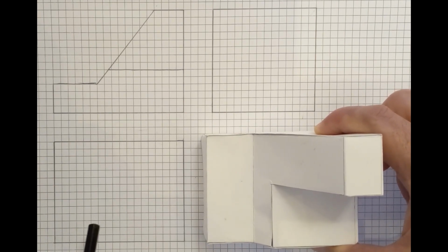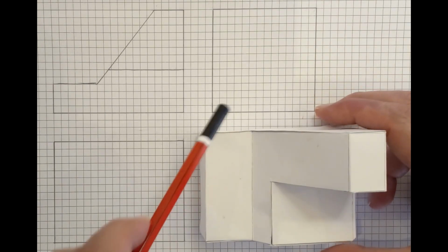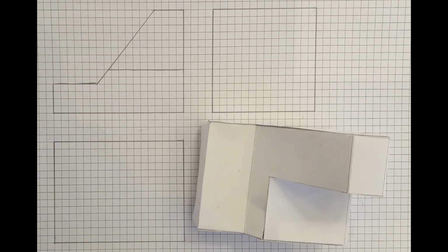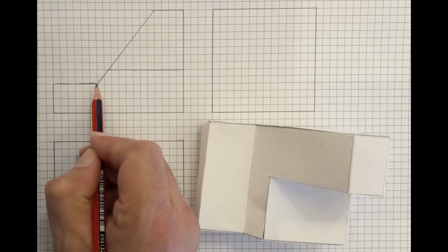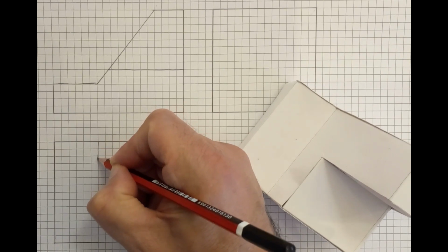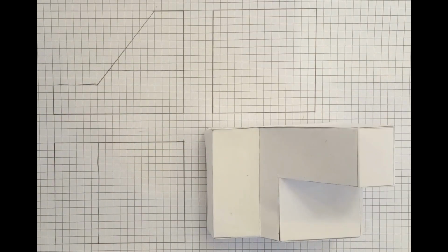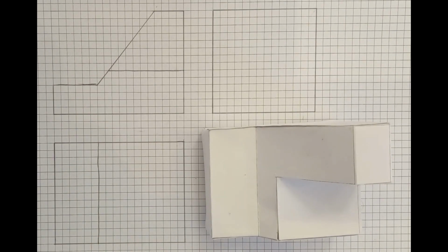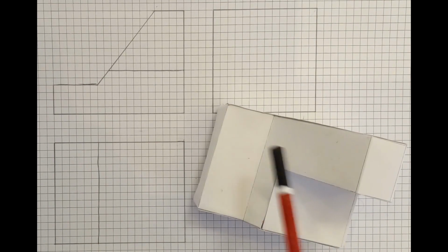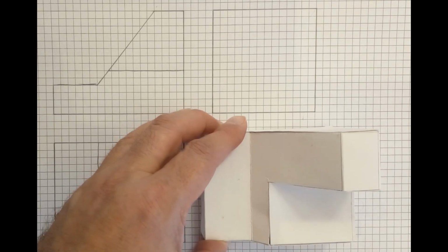Where exactly? We can get the dimension from the drawing or from the front view. This line is represented in the front view by this point. So aligned with this point, we will draw a vertical line in the top view like this. So this is the rectangle. What else do we have? We have this inclined surface as an L shape, and we have 2 other rectangles.